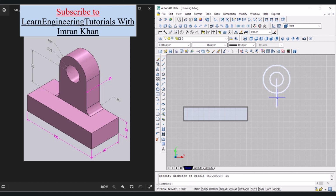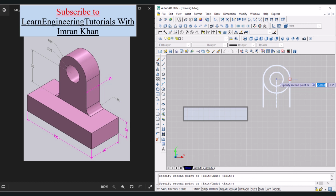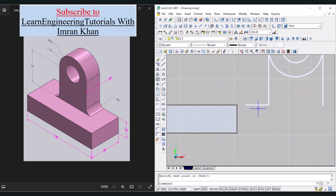And now we have to copy this line, click on this line, click on this copy icon, select this as a base point, click on this quadrant and this quadrant, press escape. Now remove this line, and now let us draw another line of random dimensions, like click over here, press enter. Now we would want to fillet these lines, so click on fillet, radius should be 8, R enter, 8, enter, click on this line and then click on this line.